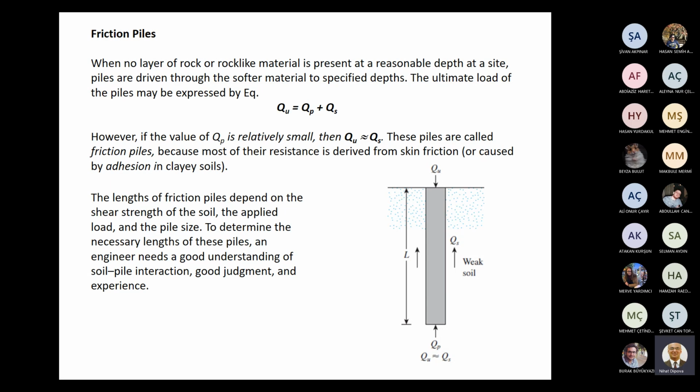Actually, friction is applicable for sandy soils, granular soils. In the case of clay soils, the side friction, shaft friction, comes from adhesion on this interface.